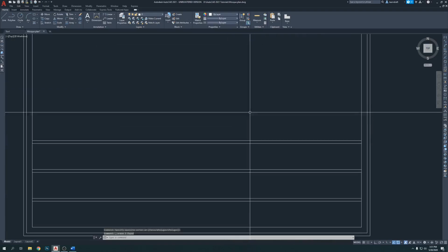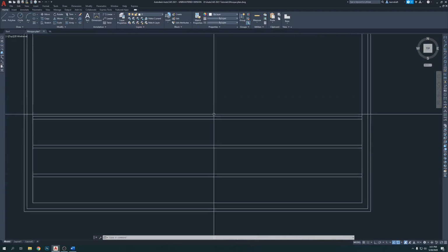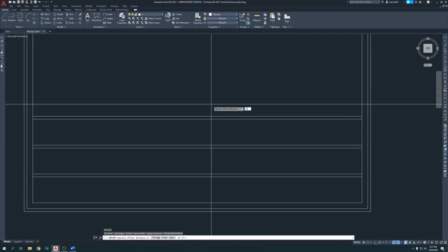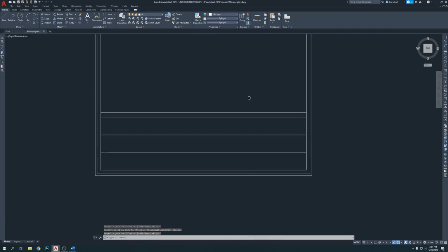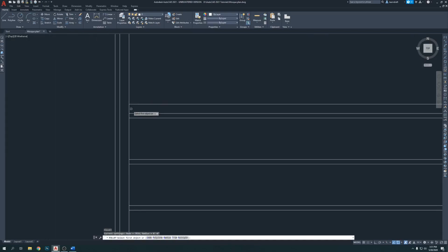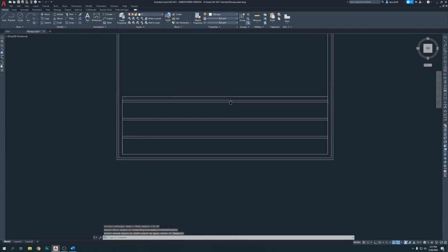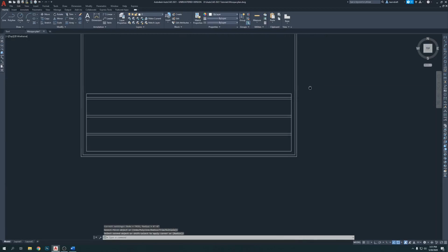Now what you're going to do? You need 1 foot here, like how you have 1 foot everywhere, like this. Offset. Enter. 12. Enter. Click here. Click there. So the line is, we have the 1 foot line surrounded. So we're going to make it fillet. Enter. This one with this one, and here. Enter. Click here. Click there.